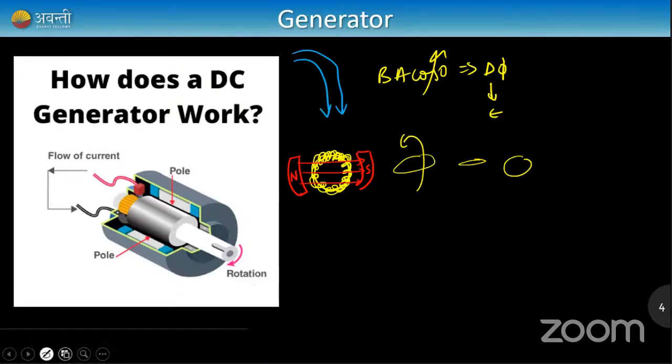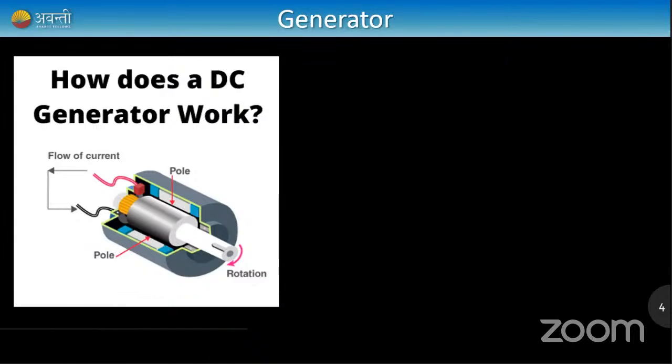See the diagram here. It's a very good depiction of the generation of electricity. There are two magnetic poles, one here and the other here. Water falling on the turbine rotates this rod, which has a lot of coil on it. When the coil rotates, theta changes, and whenever theta changes, the flux changes. That's a very simple idea.